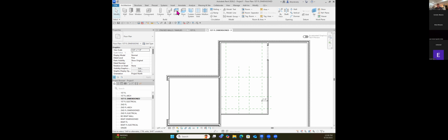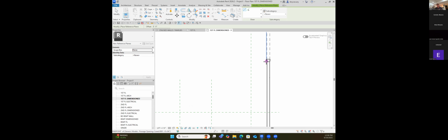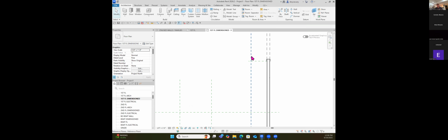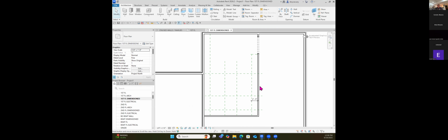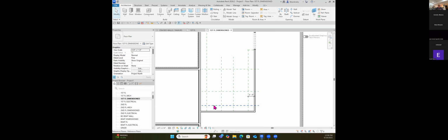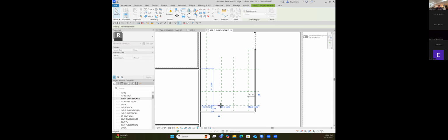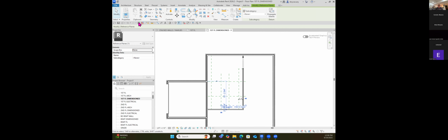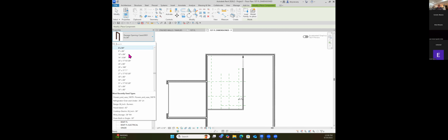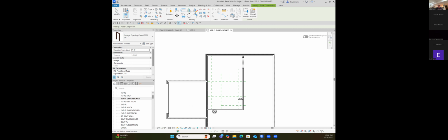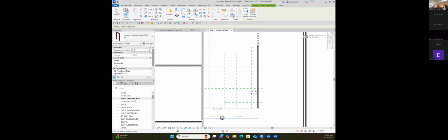So now I know that my countertop probably shouldn't go any farther than that. So real quickly, I've laid out the layout for my kitchen, and I think I'll pull this back to here. We'll put another opening over here. Architecture, component. Well, click on there. I'm going to look for a narrow 2'4" opening. That's good for now, and I'll put an opening right there.